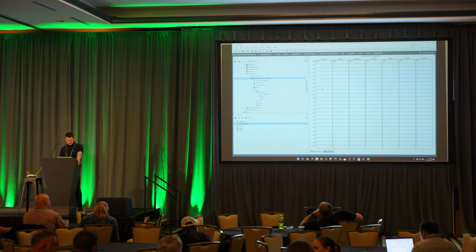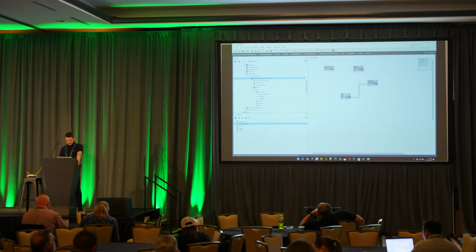And let's build a schedule from there and set it to 73. Okay. So now our schedule is built. Every day we'll have, by default, the 68 Fahrenheit when it's not occupied, and 73, and let's do that, apply that date from Monday to Friday. So the schedule is done, we can go back.